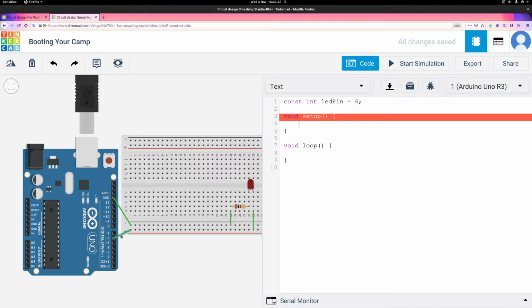And what that means is that this digital pin can either be an output, so it can output a high or a low voltage, or it can sit there and read a high or a low voltage, and that's its input state. So in that way, it can act kind of like a binary multimeter, in that it can tell you if a voltage is high or if a voltage is low. These analog pins over here act more directly like a multimeter, and we'll get to see how those work a bit later.